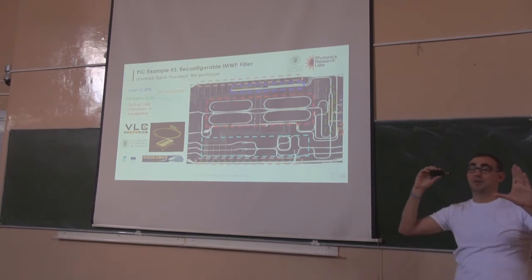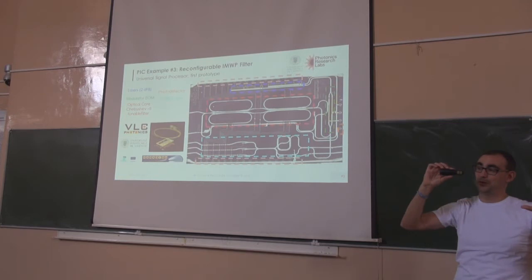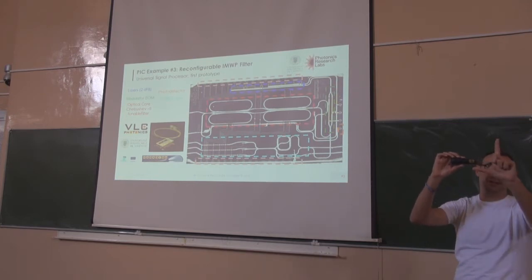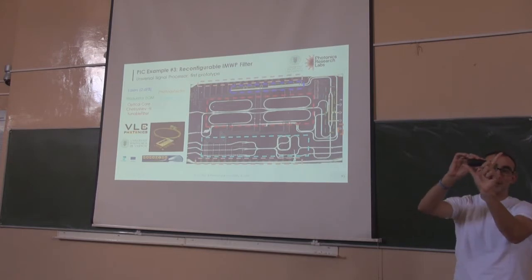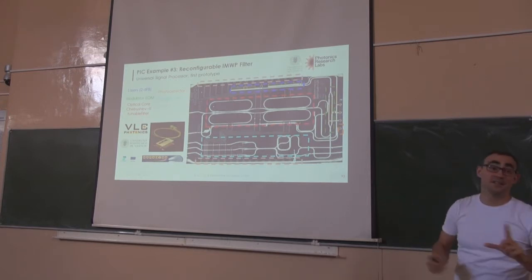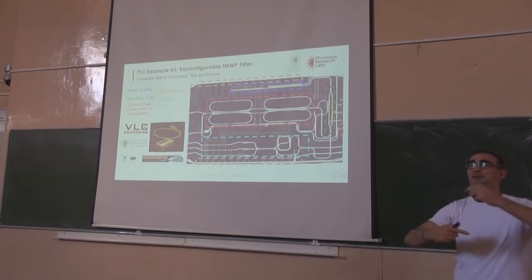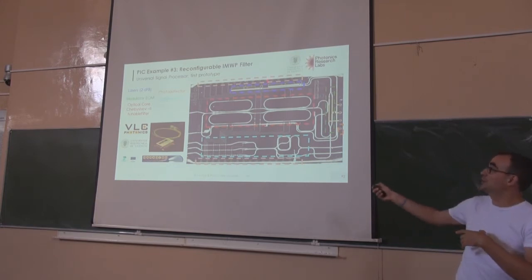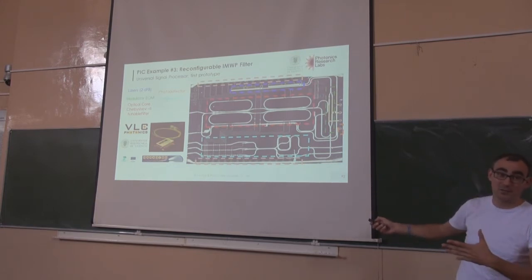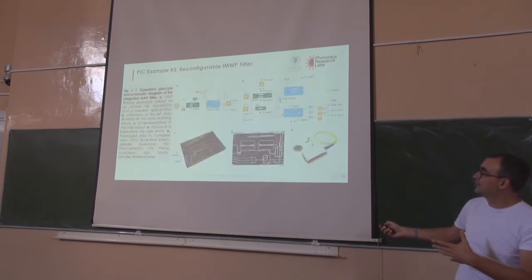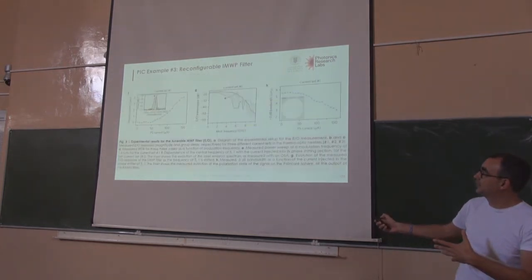That means that even when you go with your straight waveguides with one polarization, then instead of hitting this polarization and nothing of this, it hits like this. So actually you are exciting this polarization and this polarization. The filter is designed to work for TE polarization. So that means you have polarization beating, and when you tune the laser, you change the polarization beating, and you are changing the filter shape.